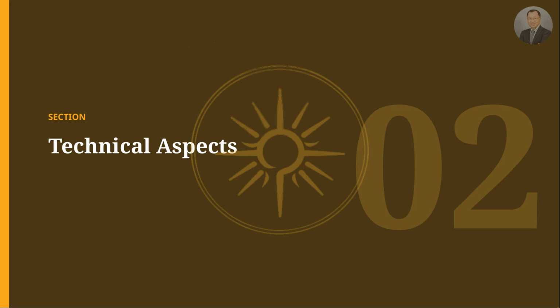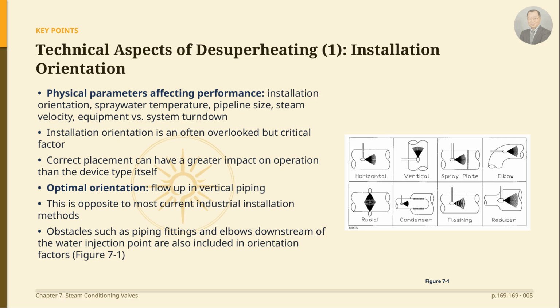Next, we turn to technical aspects. Let's look at the physical parameters that affect the performance of a desuperheating system. These include installation orientation, spray water temperature, pipeline size, steam velocity, and equipment versus system turndown. Among these, installation orientation is a frequently overlooked but critical factor in system performance. Correct placement of the desuperheater can have a greater impact on operation than the style of the unit itself.